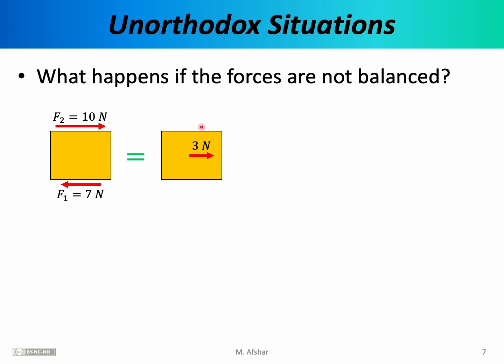But in addition to accelerating to the right, the block will also deform, because in addition to this 3 newtons, there is a further 7 newtons being applied to the top face. That 7 newtons is balanced by the 7 newtons here. These two forces do not accelerate the block to the right. Instead, they deform the block, and we know how to calculate the deformation of the block. We've already seen equations for that.